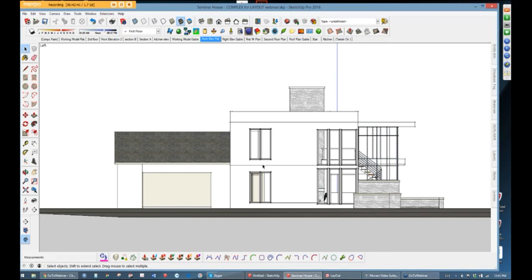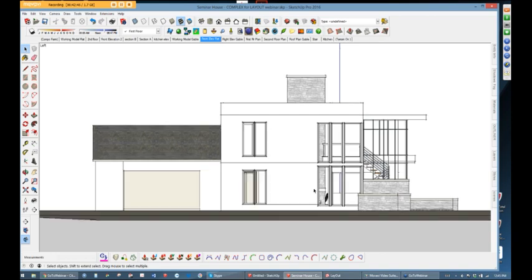What I like to call it, and there's another man out there, Matt Donnelly, who does a lot of this layout stuff, has a book out there called From SketchUp to Layout. So if you want to look for that, it's not a bad reference. We create what's called a mask. So I'm going to set a plane in behind this wall that we're looking at and mask off all this stuff in the background. And how do we do that?